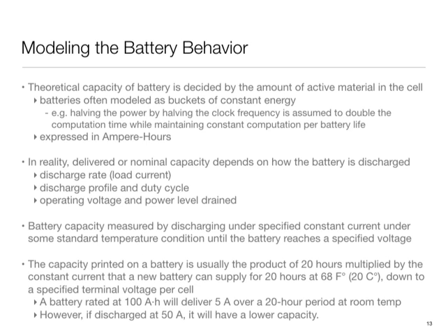And the other thing, which is less noticeable, is that if there is a significant mismatch between the load and the battery, then the battery can die very rapidly. If I draw current out of it at a larger rate, then it doesn't live up to the expectation that we had. So I can draw less if I draw at a larger rate.